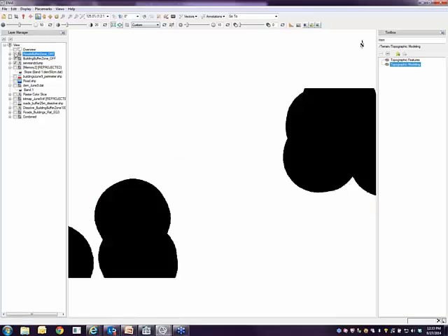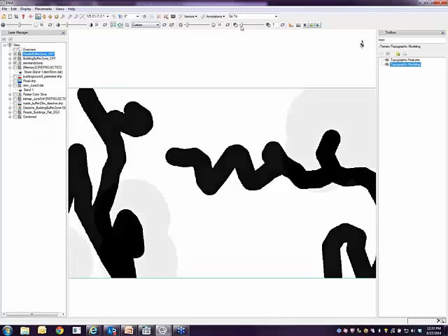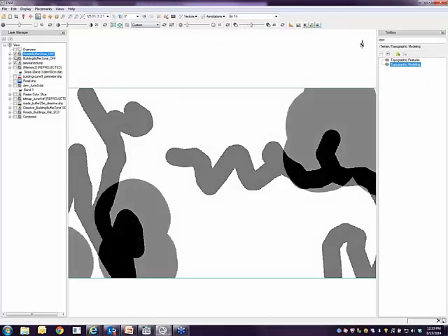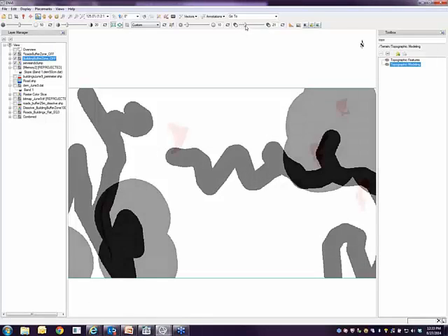And when you start to combine these, by changing the transparencies, you can see that we have some suitable layers, maybe here, over here, that might be suitable sites that fill all criteria. And to do that as a data fusion project, we're just going to use bandmask. And that's just band 1, which is the road buffer layer where those road zones are off, plus the raster where the building zones are off, plus the area where the non-suitable sites are off.